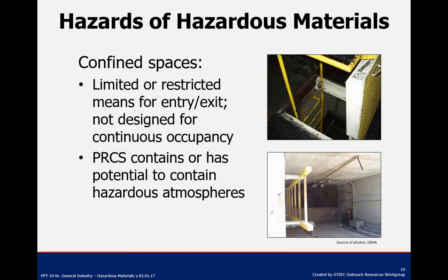Confined spaces. Confined spaces are considerable because they are not necessarily designed for people, but are large enough for workers to enter and perform certain jobs. A confined space also has limited or restricted means for entry or exit, and is not designed for continuous occupancy. Confined spaces include, but are not limited to: tanks, vessels, silos, storage bins, hoppers, vaults, pits, manholes, tunnels, equipment housing, ductwork, and pipelines.